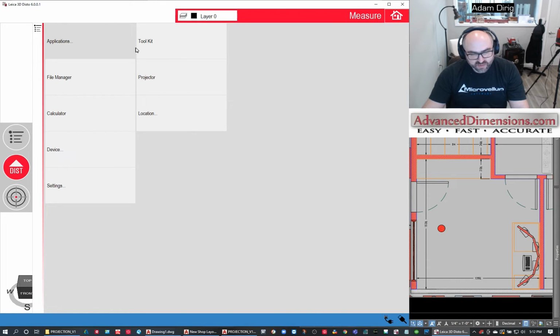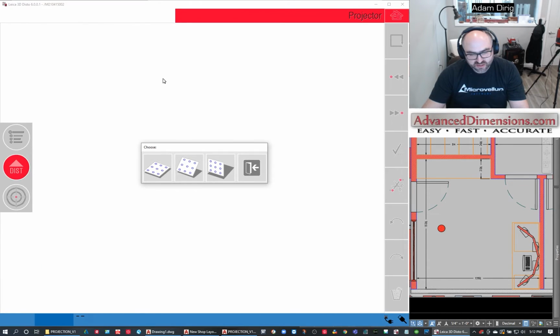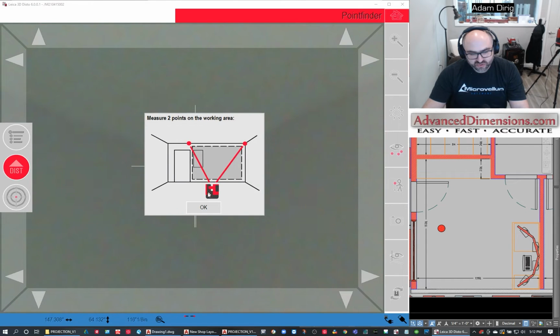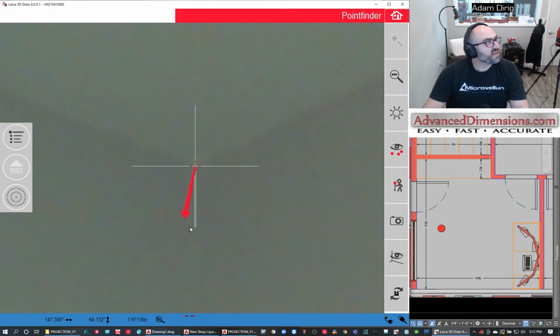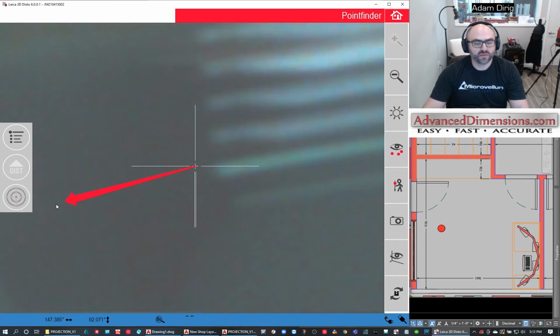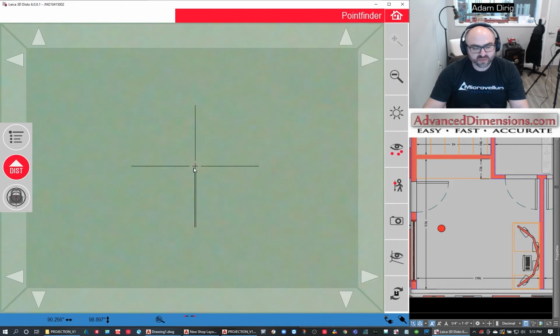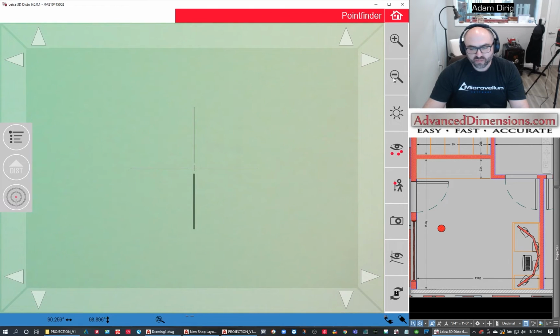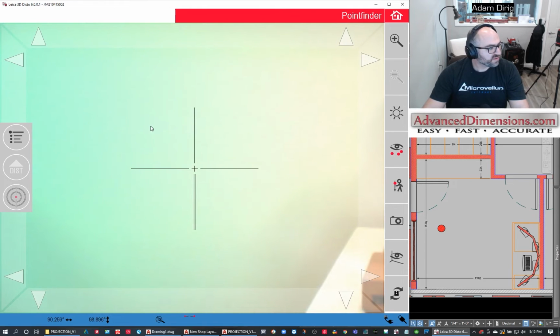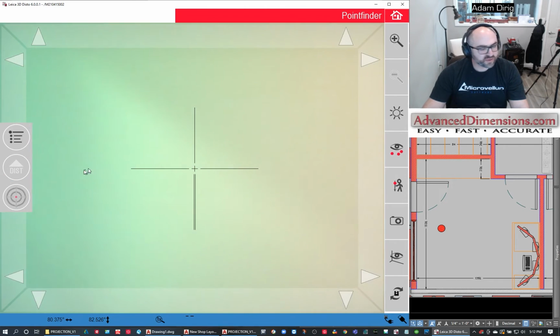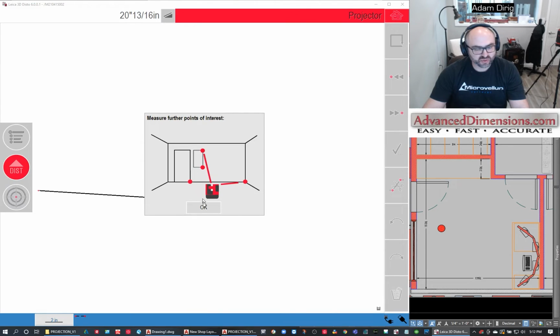And we'll do the same thing, but this time we're going to say, hey, I want to project. I want to project on a vertical. I want to pick my 2 points. And again, these 2 points are kind of random. They're kind of similar to the first 2 points that I would take when I'm establishing the file. Same concept applies. So give it a second to catch up here. So I'm just going to come up and take almost the same spots that I took the first 2 points. These have no relation to the file orientation. It's really just to establish where that plane is.